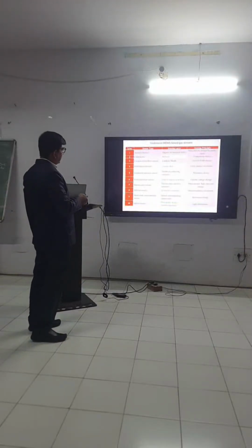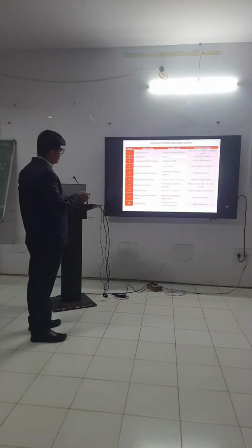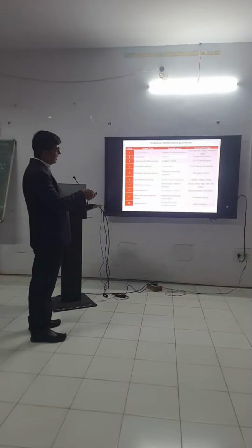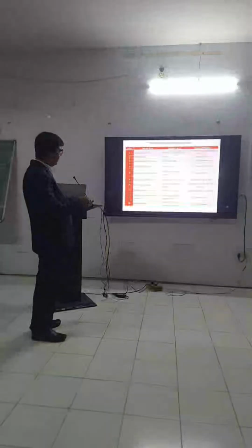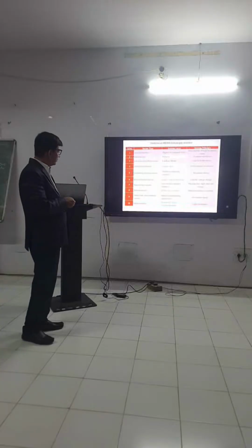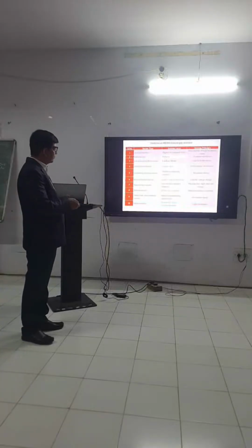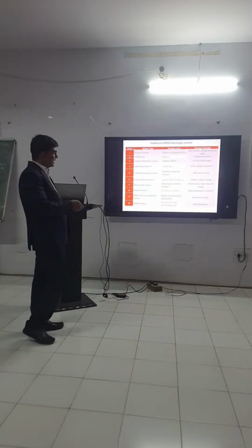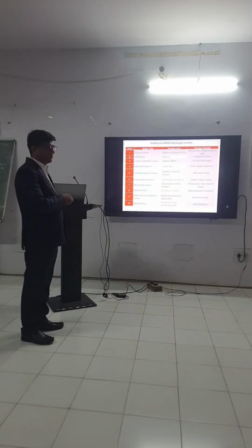Then we have a calorimetric type of sensor. So you can see these different types of sensor and what kind of sensing layer they require and what the sensing principle is. So in our case, we have a change in mass or density, and due to the change in mass and density, there is a change in the frequency. Clear? So you have to identify what kind of sensor you want to fabricate, and based on that you have to select a particular sensing layer and how this sensing layer plays a major role to change the principle of that particular sensor.